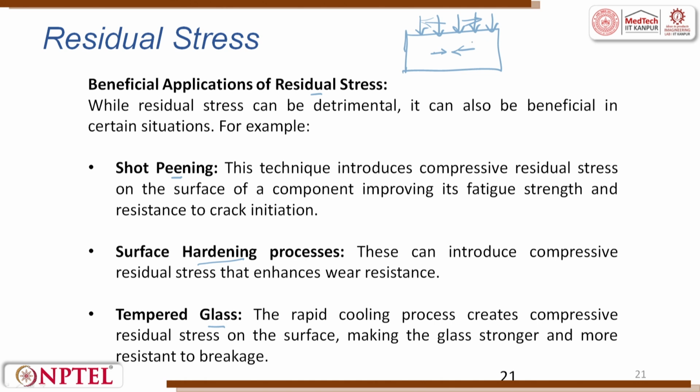So, how do you do it? Either you hammer it or you use a ball, like a shot. All these shots hit on the surface. Because of hitting on the surface, there is a compressive stress. This tries to bring in a benefit in the performance. This will try to close the cracks which exist. So, it improves the fatigue strength and resistance to crack initiation.